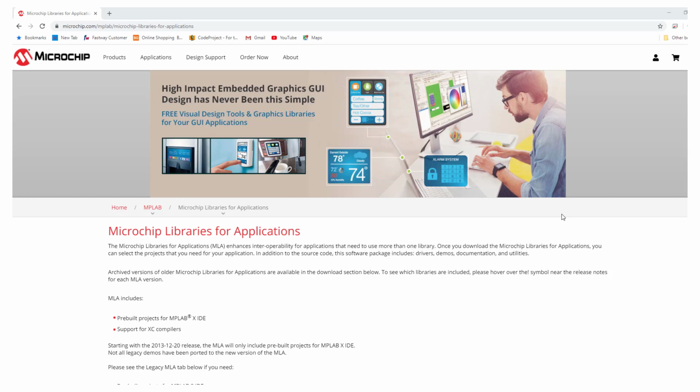Microchip supplies a full portfolio of USB enabling products including devices, hubs, transceivers, and power controller. Some PIC16F1 and PIC18F series can be used as USB devices. USB devices are peripherals that can be attached to a USB host like a PC. Typical devices include products such as keyboard, mice, or medical devices. Some PIC24, dsPIC, PIC32MM, PIC32MX, and PIC32MZ series can be used as both device or host.